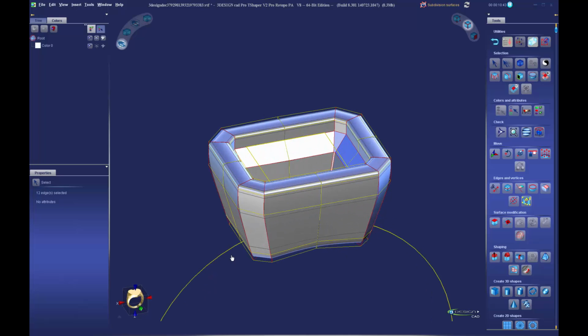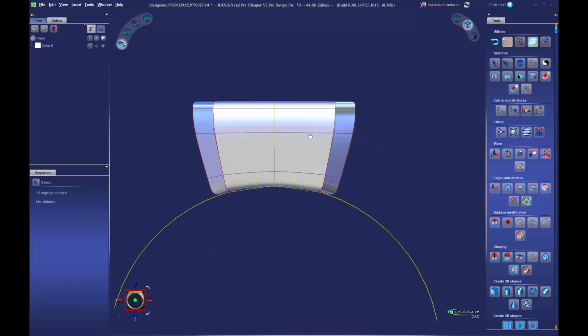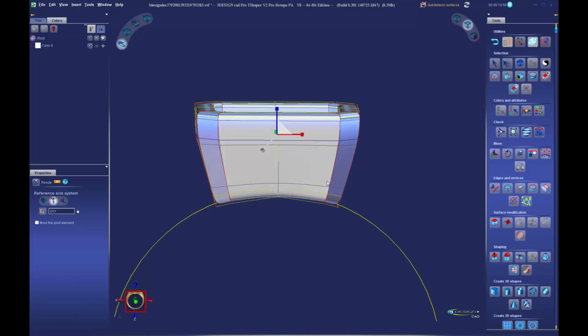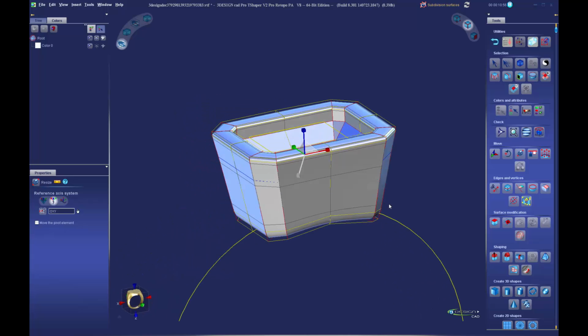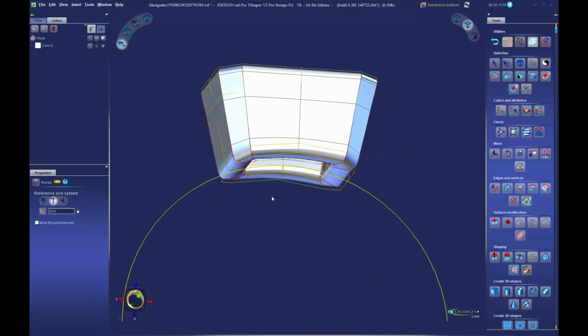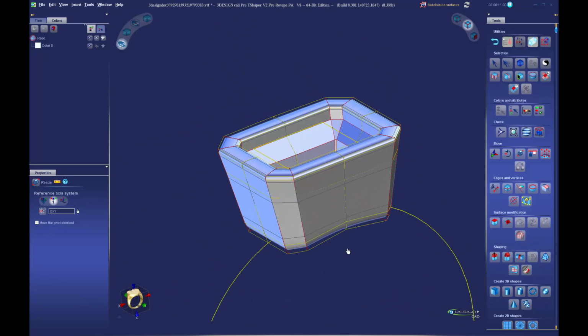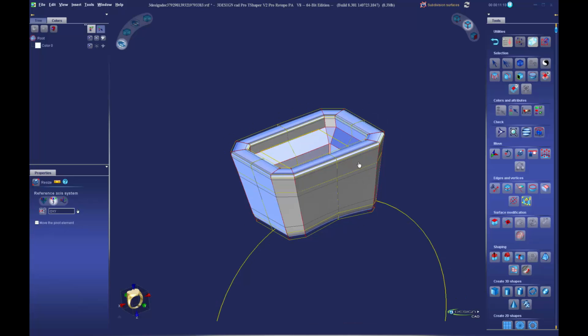Okay, so that's starting to clean up a bit. If I go to this edge and do an edge loop and a scale, I can kind of fix that. So it's straight up and down, like so. And like I said, that's pretty much it. Once you've got it all cleaned up, you've got a nice straight, clean bezel with nice filleted corners. You could use it as is, or you can customize it. We can make some crazy shapes, do some cutouts.